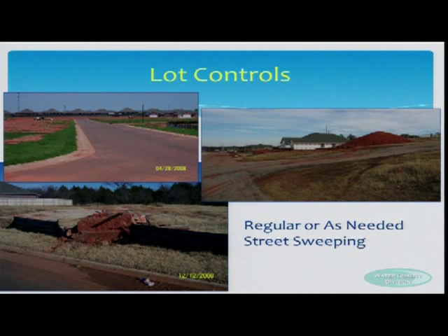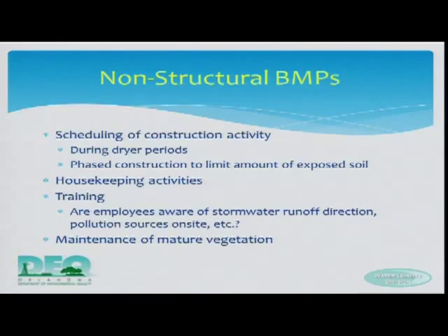Some curbside sod goes a long ways towards keeping sediment on the site. Street sweeping may be called for. You may need to go talk to the operator of the dump truck who backed up there and dumped stuff right on your silt fence. So, count on those guys not necessarily knowing what that stuff's for.